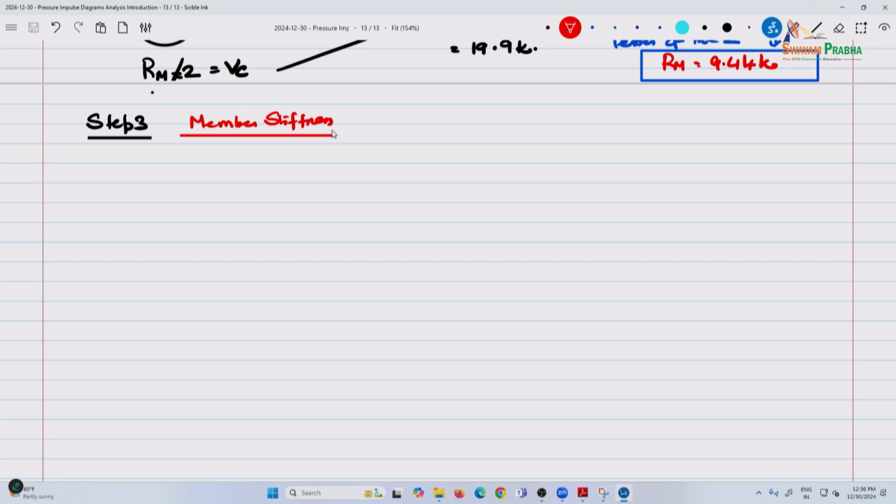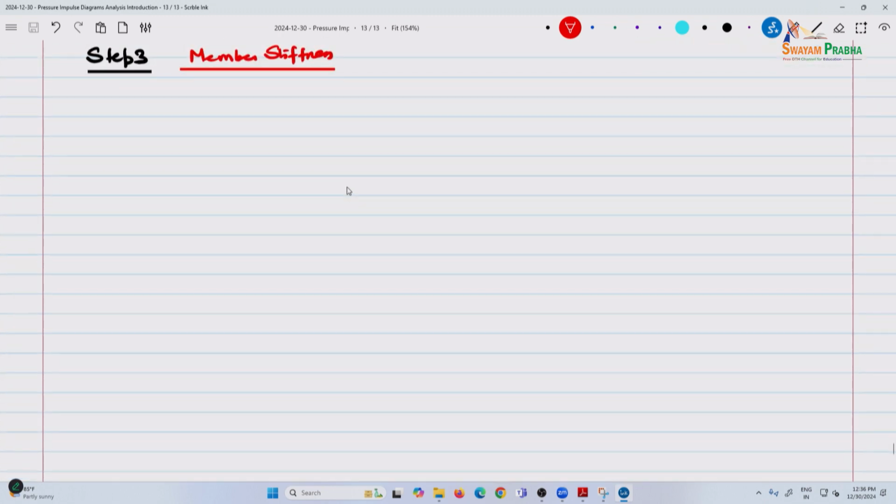Okay, I think I'll go through it. If we go a little longer, let me go through it anyway. What do you think? Go over it? Okay. So, for a simply supported beam, KE is 384 Ec Ie divided by 5L cubed.